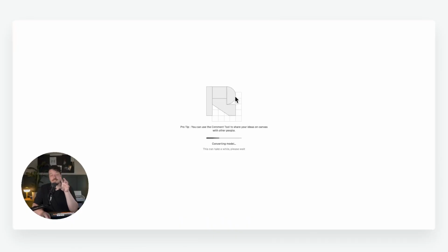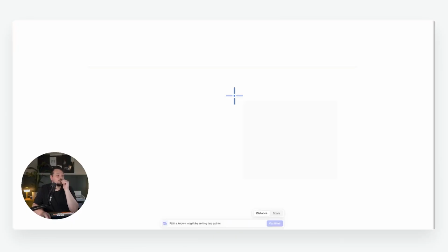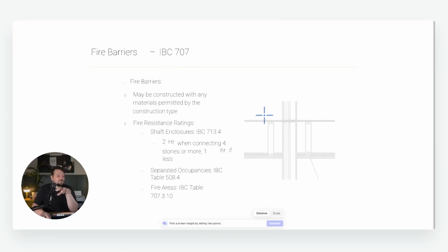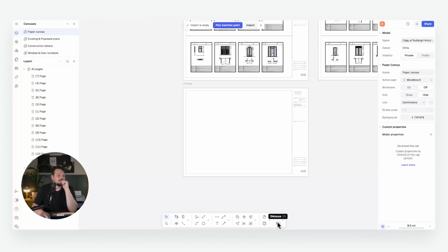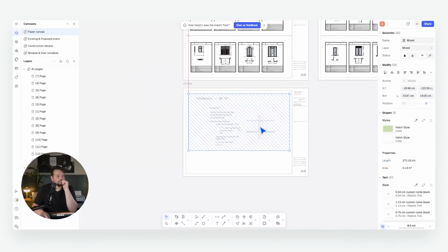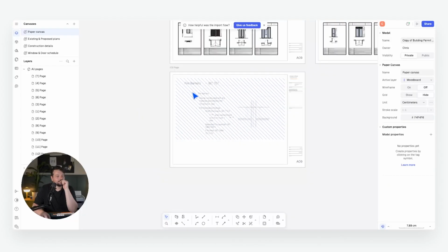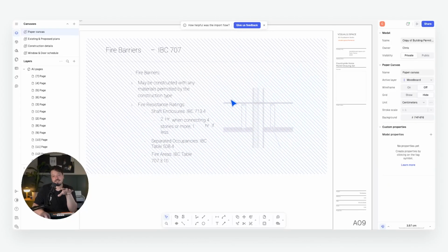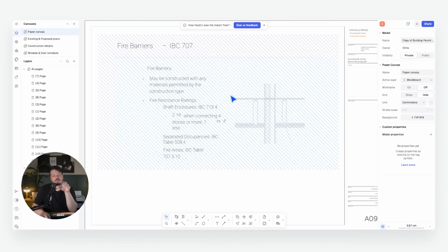It will then take me to a separate import window, and then I can see that PDF page there. As this drawing isn't to scale, it's a PDF page with some information on it, I'm just going to put in 1:1 as the scale, so then that will come out at the size of the document. I'll press continue, and then I can pick an insertion point on my page. You can see there, that's inserted that PDF document with our standard detail that was included within the PDF.